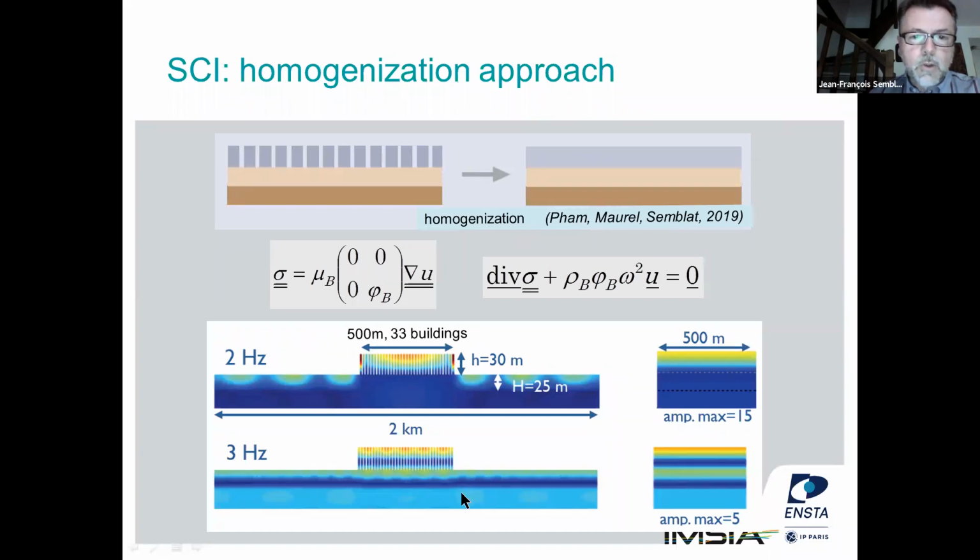So it may be larger than the building width, but smaller or of the same order as the building height. But we have to consider that the seismic waves are mainly body waves, either pressure or shear waves, or surface waves. And we also have to consider that for the buildings, we may mainly have bending or rocking. So it is a different kinematics.